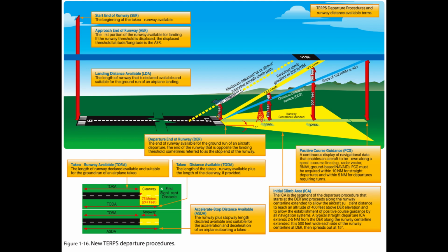Examples: (2049 - 1221) divided by (0.76 times 3.1) is equal to 351.44. 48 times 3.1 plus (2049 - 1221) divided by 3.1 is equal to 315.10. Round to 352 feet per NM (asterisk, military only). Round to 316 feet per NM. These formulas are published in FAA Order 8260.3 for calculating the required climb gradient to clear obstacles.